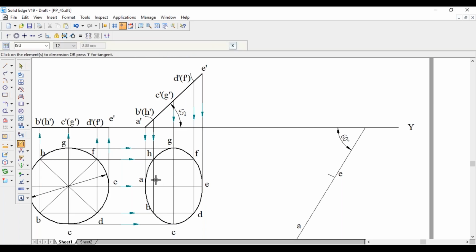There is this distance, 5.18 mm, same as this one also. This is also 5.18 mm only. With this point as center, 5.18 mm as radius, cut an arc. Similarly, with the other point as center, 5.18 mm as radius, cut another arc.